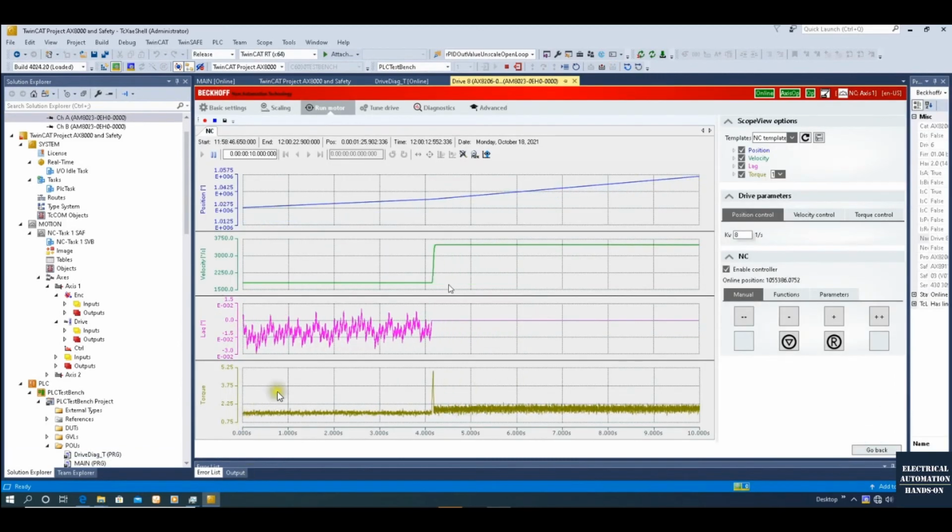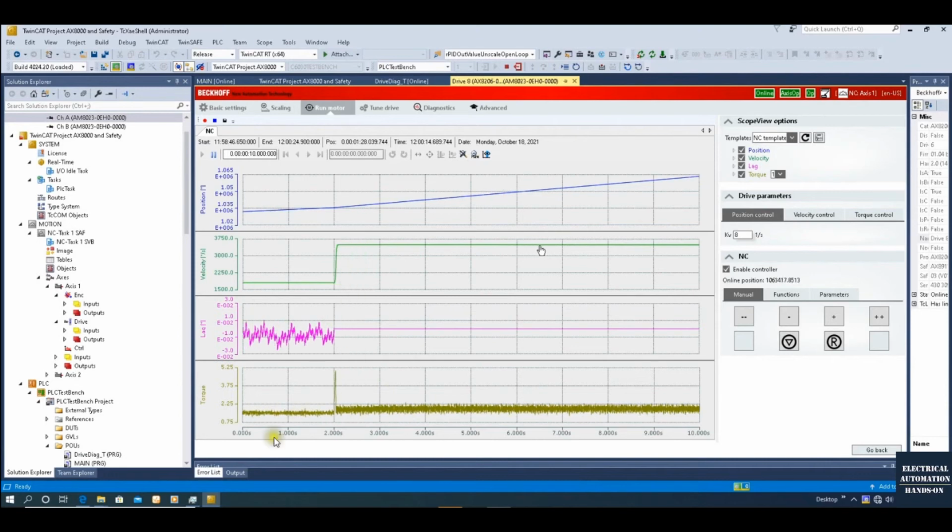Okay, we can see here. This is interesting now. So as we can see, the speed reached to the highest limitation here, 3500. We set 5%, but actually the system does not need the 5% because now the motor is doing the free run. So the motor just delivers the torque, the actual load it needs is just a 1.6. Our set point is 5% because now it's a free run.